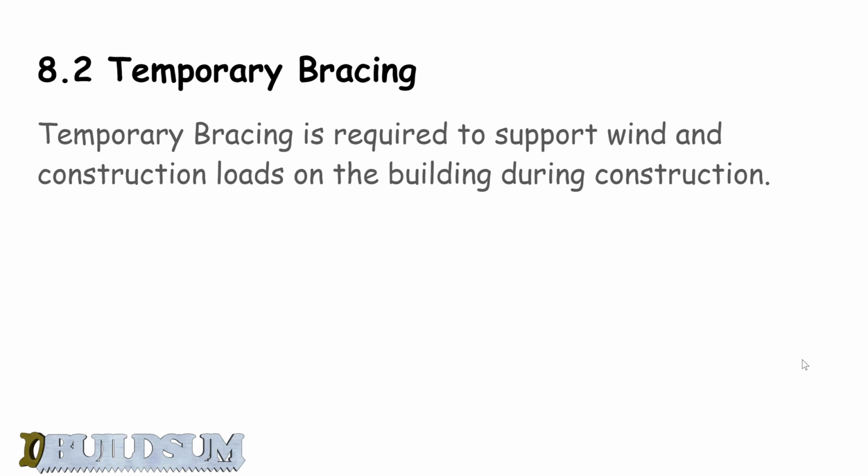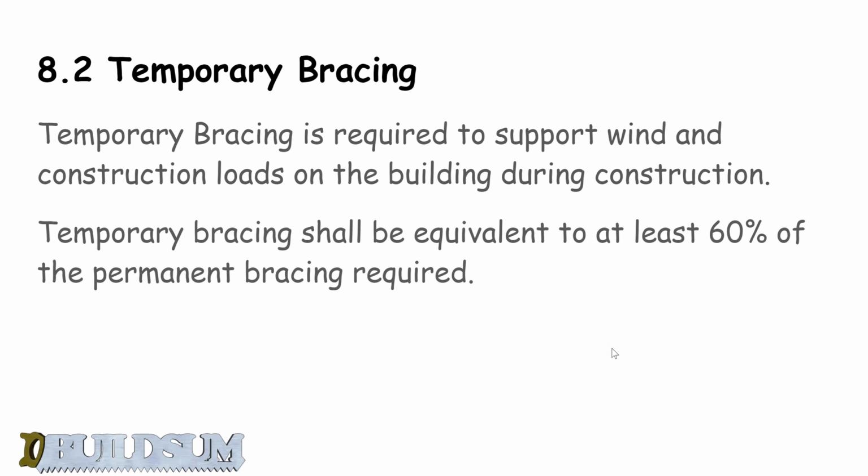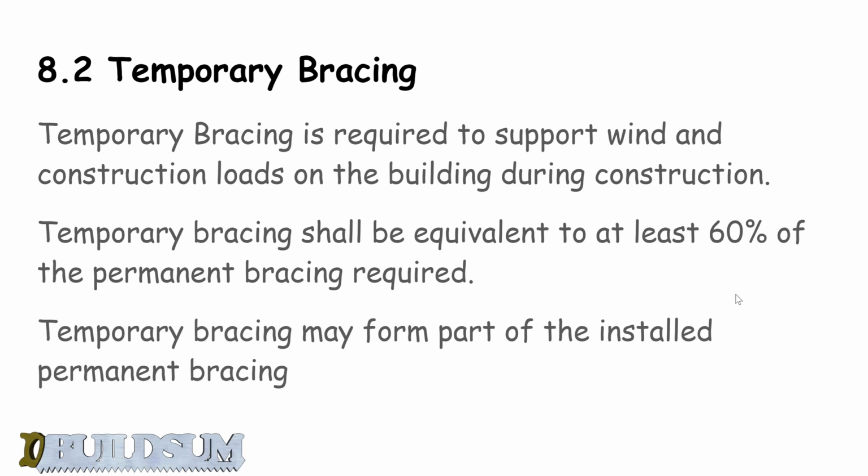Just a note about temporary bracing. Temporary bracing is required to support wind and construction loads on the building during construction. Temporary bracing shall be the equivalent to at least 60% of the permanent bracing required. It's not something I really thought about when I was erecting wall frames and that sort of stuff, but they say 60% temporary bracing. And if you do install temporary bracing and you want to leave it in place, it can then become part of the permanent bracing.